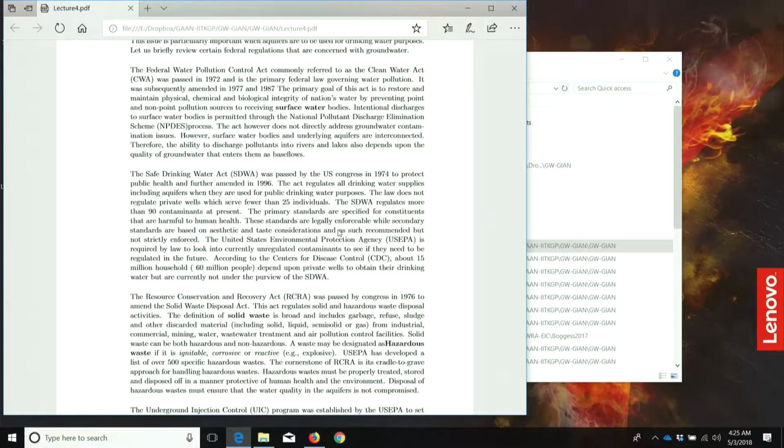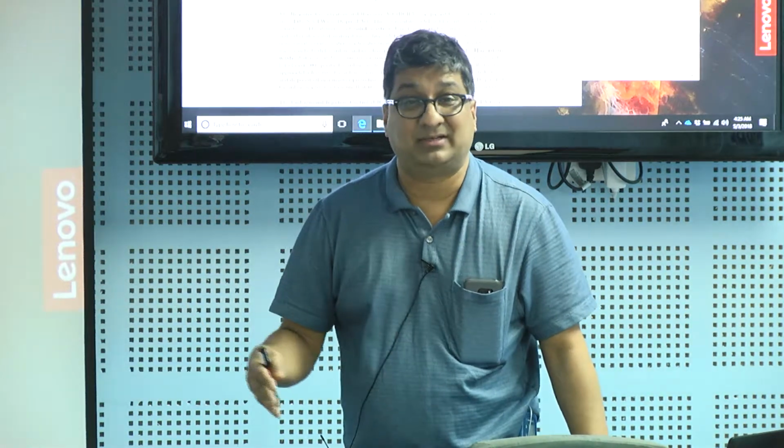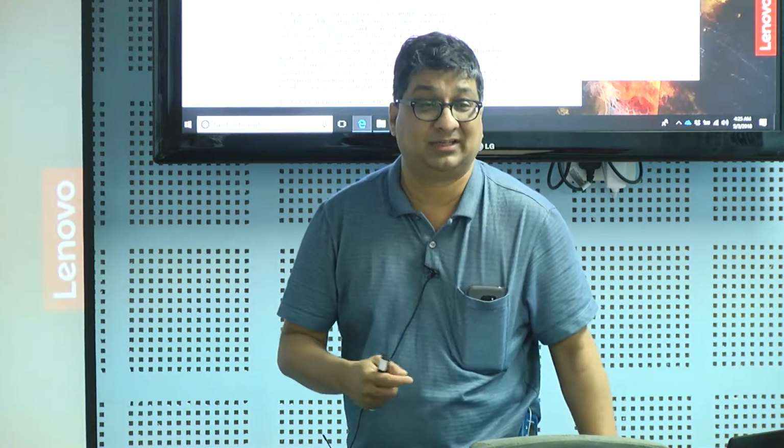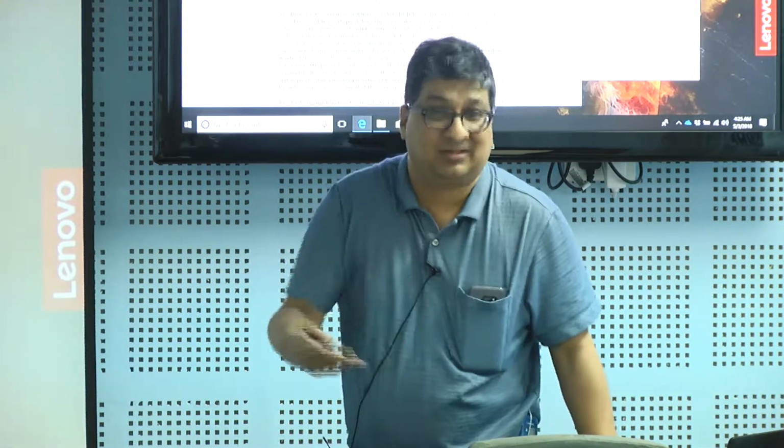Okay. So a RCRA facility or a disposal facility, which is one of those hazardous waste landfills, had to have certain wells, and had to have a monitoring program that says that we will continuously monitor some of these wells. Back in the day when the act came out in 1976, continuous meant once every 3 months. Nowadays, on some chemicals it's almost every day, on some chemicals it's once every 3 months, and so on and so forth, depending on the chemical that you're looking at.